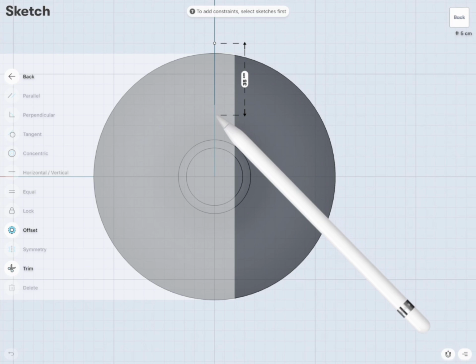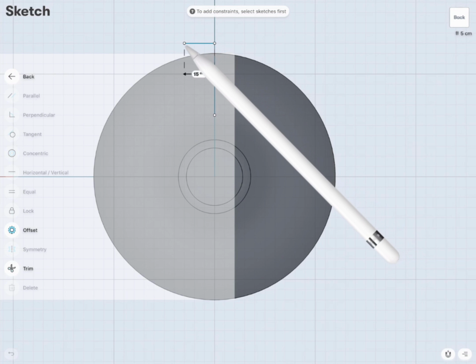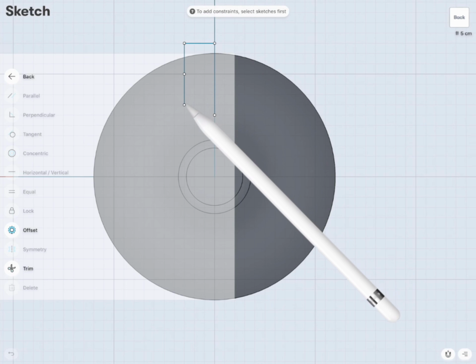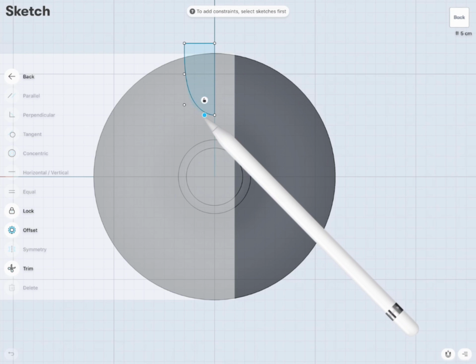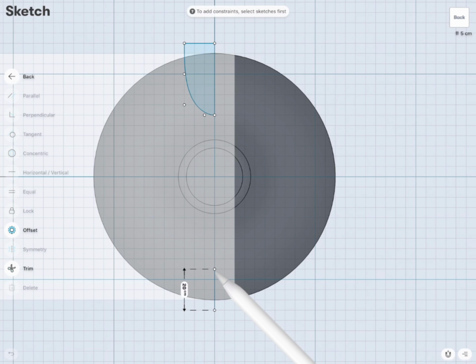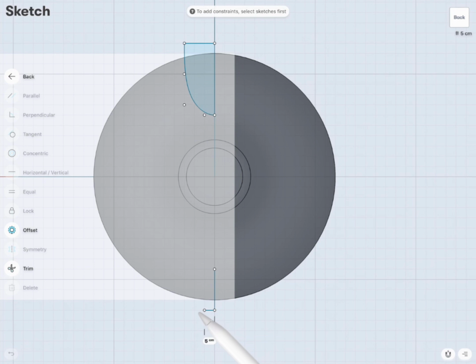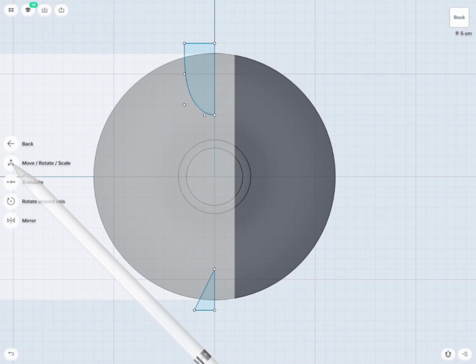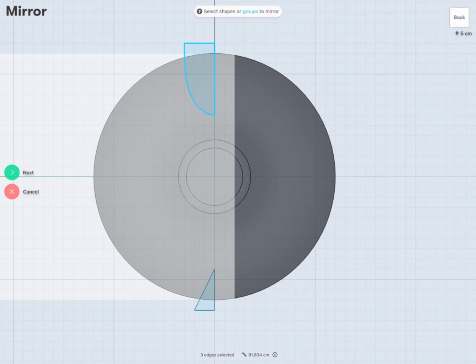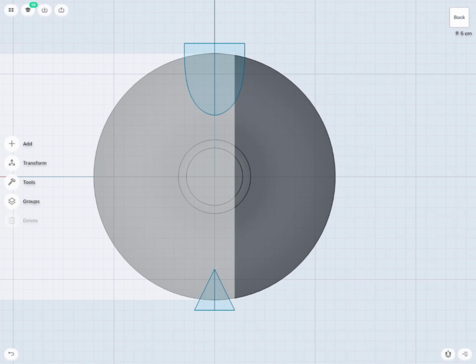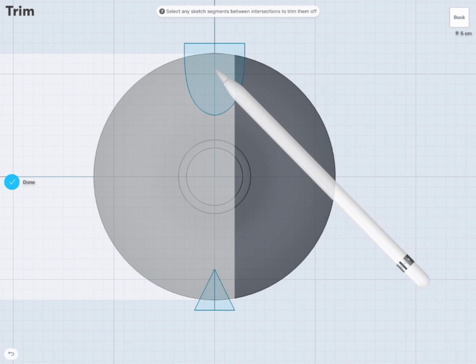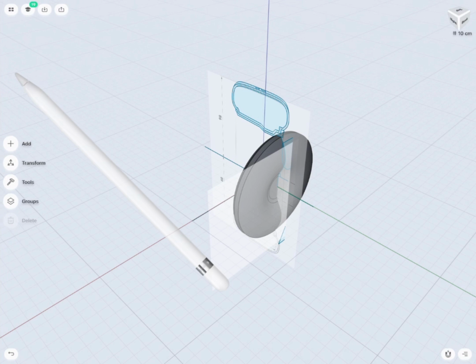Use lines for your purposes to help yourself design what you want to design in the way you've sketched it before, as I did. As you can see right now, I'm creating the symmetry lines according to the profile curve, and then I'm creating profiles I'm going to use to cut through the objects. Those symmetry lines are also very helpful to mirror, as I did right now. I'm going to trim the useless curves and go back to the perspective view.